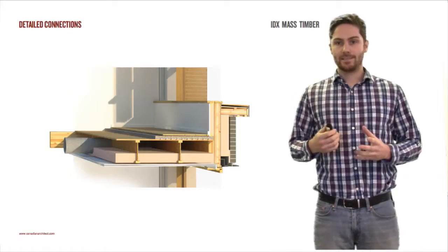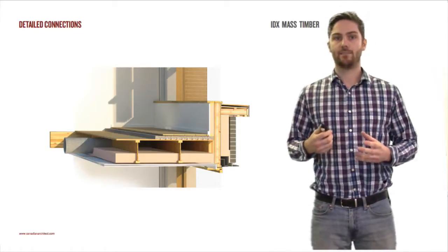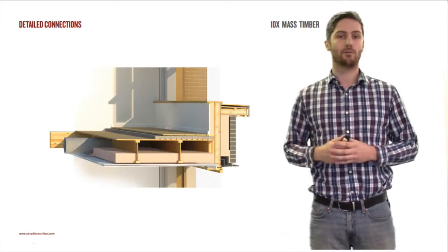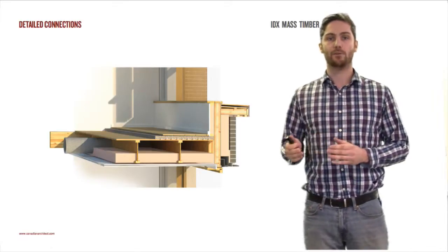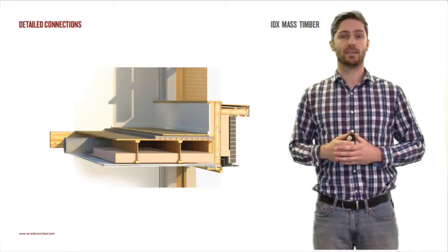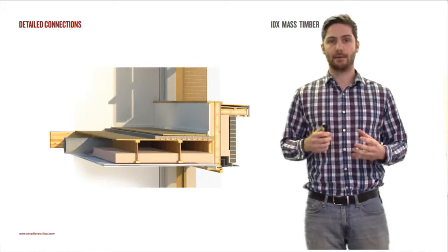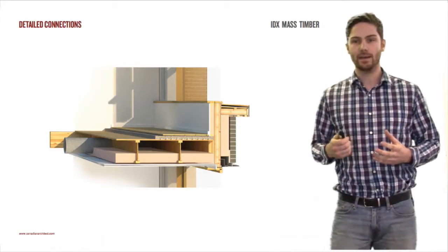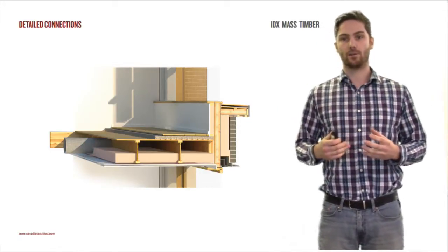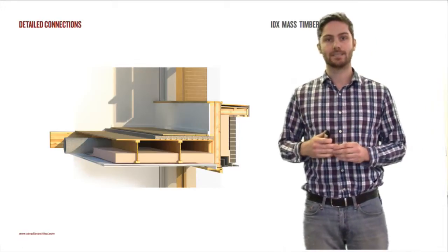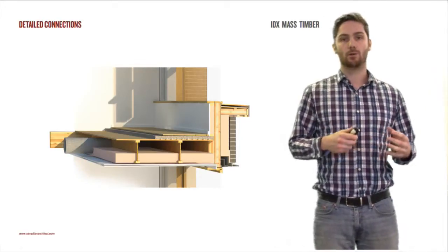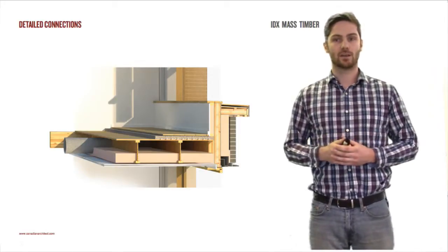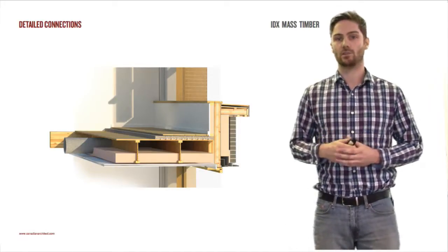I want to note that these detail connections haven't been engineered or sized proportionally, but what they are is a visual for us to see where we would have to move forward or where further research is going to have to be done for a connection type for a CLT panel. Because CLT is so new, connection types are still really being implemented and researched. And so these are just more of that visual aid to see this is the type of connection we've seen work maybe in glulam or other preliminary CLT structures. And so we wanted to create that visual.